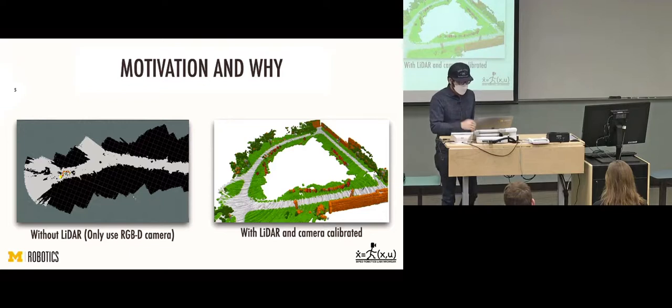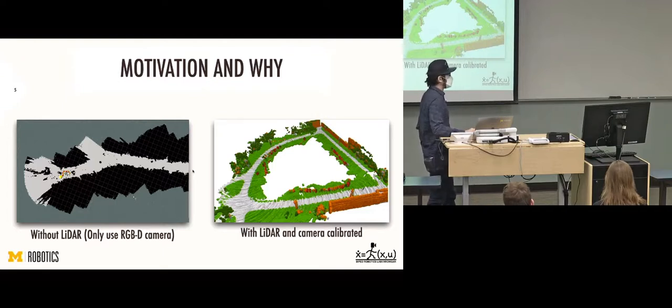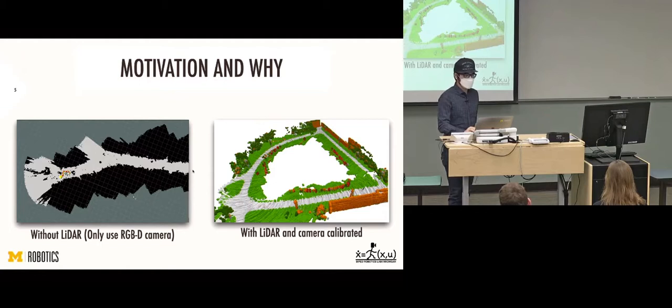of a sensor. Another benefit of this is you can see on the left-hand side. What Bruce was saying there is Cassie doesn't have a head that can turn. So when she's walking forward, all she can see is forward. But if you want to be able to plan to turn left, you have to be able to see far and wide. What happens is the LiDAR, because it's spinning 360 degrees, is like having eyes all over your head.